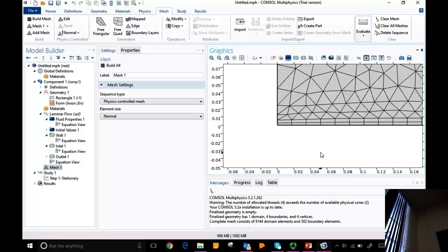What you need to do in building the algebraic equations for differential equations, for each domain or each cell, is know where the coordinate locations are. But you also need to know which one is connected to the next. So if I have a grid like this, I need to not only keep the coordinates of these three elements, but I need to keep the information that this is connected to the neighboring 4 cells. Okay? In this case, I don't need that because it's structured. They're all layered one after the other. So this is called a structured mesh or the mapped mesh.